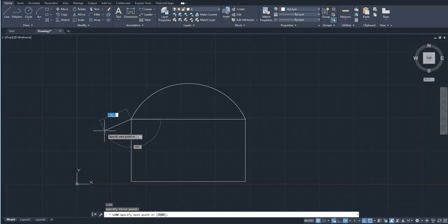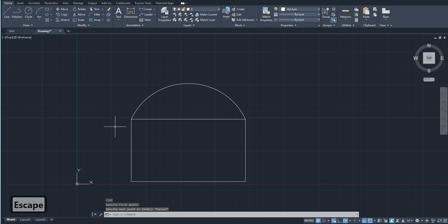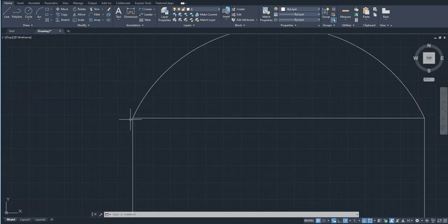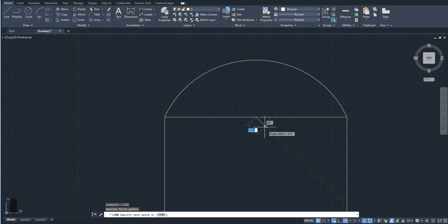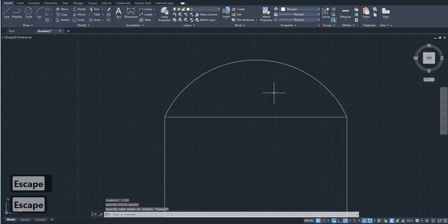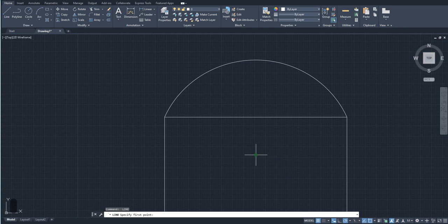Now I'm going to be telling you the different types of object snaps that are in there. First, I taught you about the endpoint already. I'm going to be teaching you about midpoint. Midpoint is basically this triangle. You can use it. Midpoint can be in a line or also in an arc or in a circle, anything. Midpoint can be a midpoint of anything. Center for this arc is here. Center can be for circles, ellipses and parabolas, or basically any curved objects can have centers.